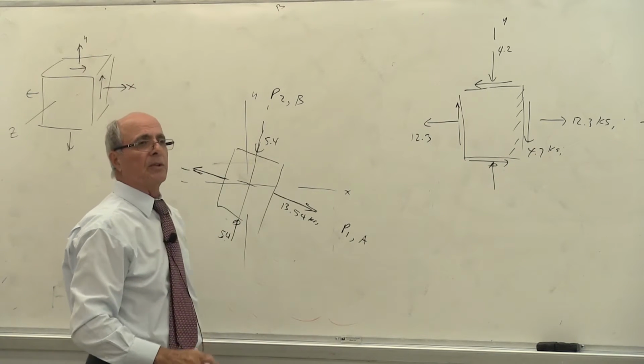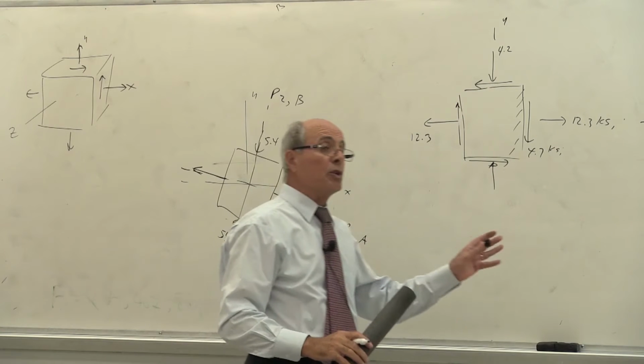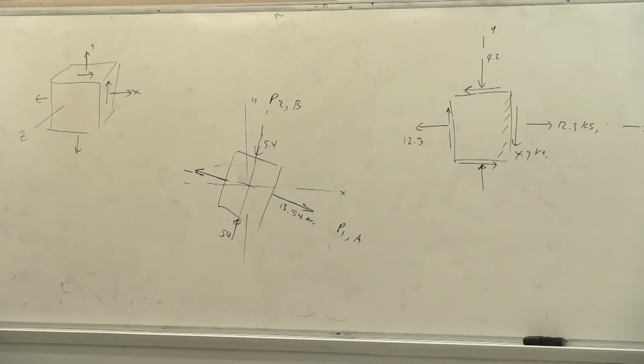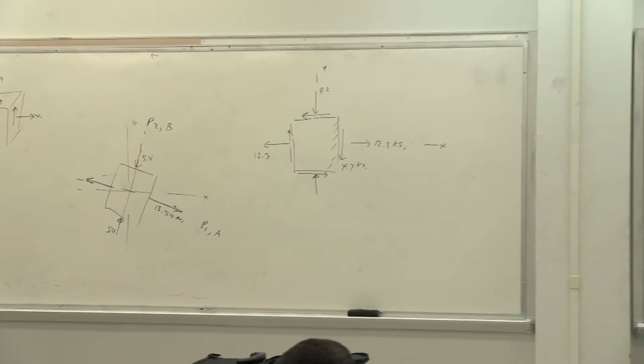Is that understood? Yes or no? Yeah. And there is no shear. Remember that. When there is no shear, it is all principal stress. Because on this circle, each point actually is an axis going in a certain direction. Everybody understand? The whole circle represents all the stresses. You find the stresses at this point. Then all the stresses in every direction are represented on that circle. And these are at the same point. You are not changing the point. However, one of them is the largest, so you design the object for this one. Is that correct or not?